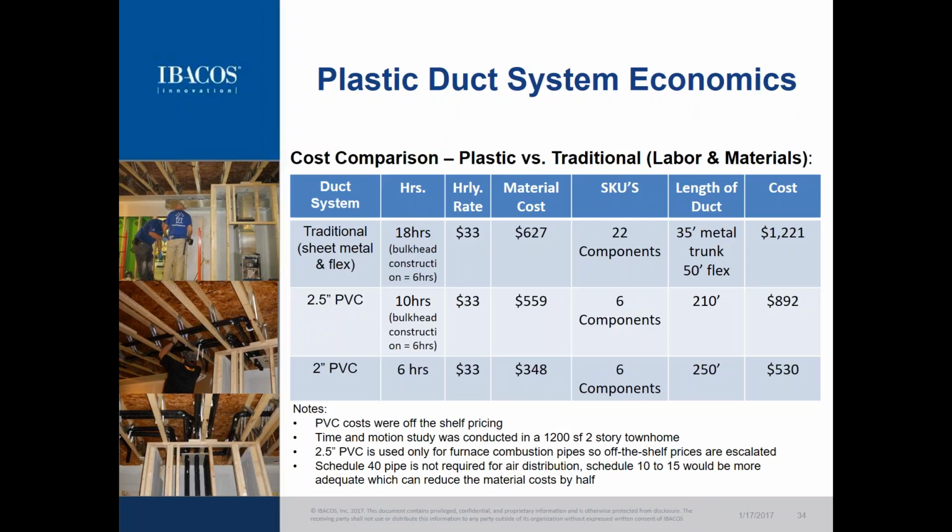So we designed the system based on our new design methodology, and the design methodology is somewhat simple. It's one size duct, one size airflow, and the airflow is obviously dependent on the amount of elbows and the length of duct, and we've done a lot of benchtop testing to understand the airflows and friction rates when we extend the duct in length and add fittings. So the design methodology was in place for the last two systems with PVC. We laid it out and integrated it into the flooring system, and then we had contractors install the system, both the traditional and the two plastic systems. And you can see here, from a material standpoint, we're getting less cost.